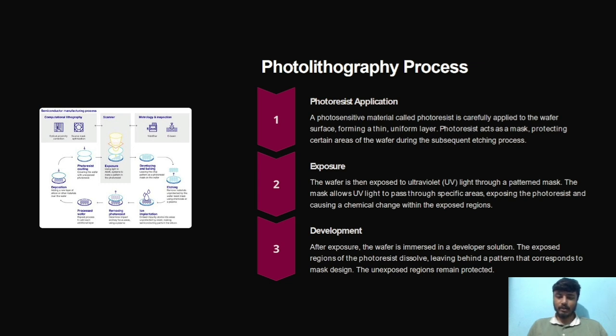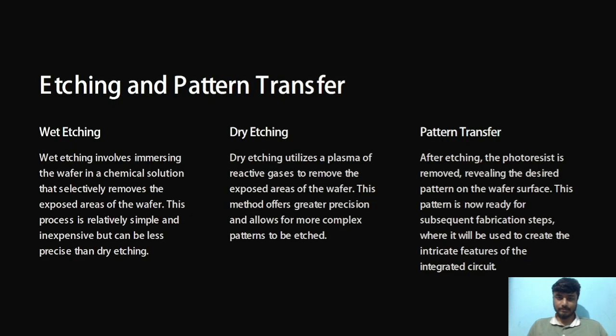After exposure, the wafer is immersed in a developer solution. The exposed regions of the photoresist dissolve, leaving behind a pattern that corresponds to the mask design. The unexposed regions will remain protected.